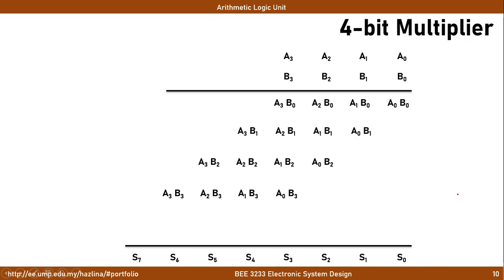Okay. So now we move on to 4-bit multiplication, which is more or less equivalent to the 2-bit multiplication with an expansion of the addition process. As shown earlier, the first string will start off by multiplying B0 A0, B0 A1, B0 A2, and continue until B0 A3, followed by the B1 process, B2 process, and also the B3 process.